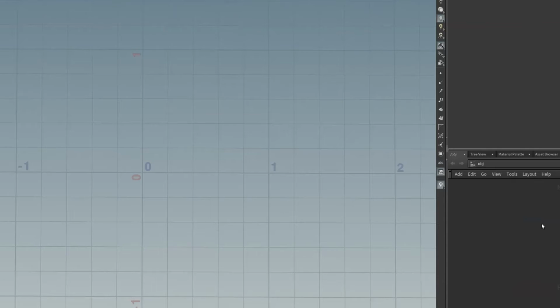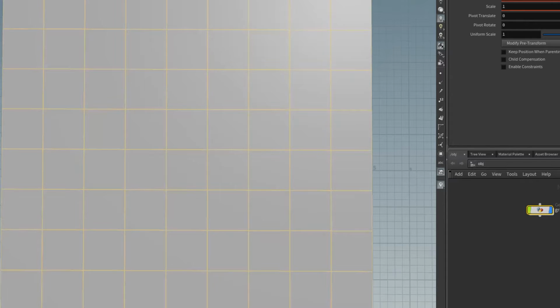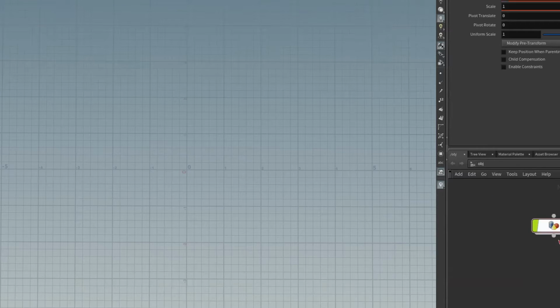from 2D to 3D. Okay, so here we start with the grid first, because our stuff is in grid, right? We have this grid, and it's really up to you how many grid cells you want. Actually, we don't want this as a grid. We should start with the geometry first, because this geometry node is actually the top of the Houdini node that you can embed all the things in.